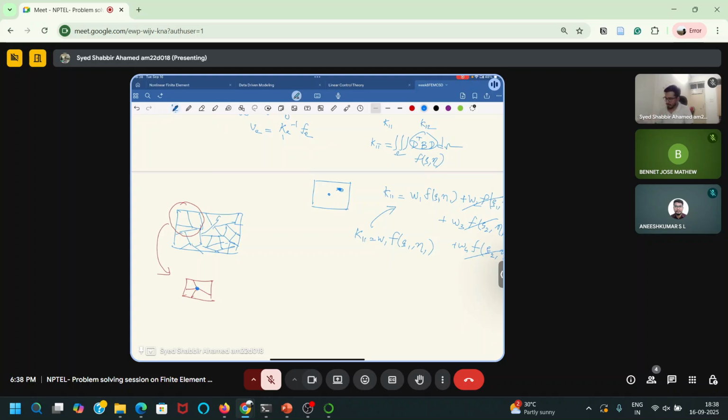One is, you apply displacements. You can apply displacements in various forms. So you apply displacement at the external nodes, and you estimate the displacement at the midpoint, and you see if the displacement is satisfying the finite element constraint. And there is also another test based on force, where you can apply force or traction on all the exterior nodes. So that is also one kind of test.